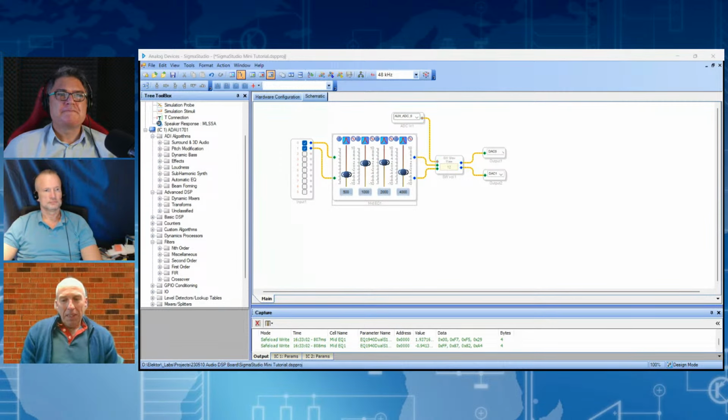Well, the ESP32 I added has a 2-channel analog converter, and because the DSP can have 4 analog control inputs, not audio inputs, I turned the 2-channel analog converter into a 4-channel. So you can use the ESP to convert MIDI signals to voltages and then control the DSP. That's one way.